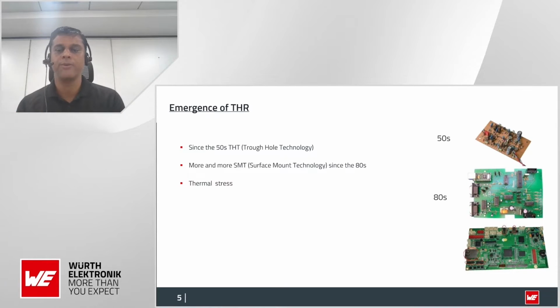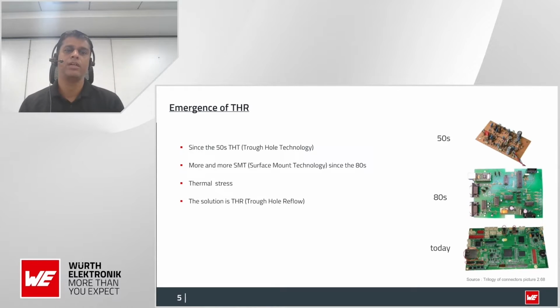So doing this, the small components on the PCBs have to go through a lot of thermal stress. Sometimes this may degrade the effect or performance of the components. So in order to overcome this, we have come up with a new technology called through-hole reflow.